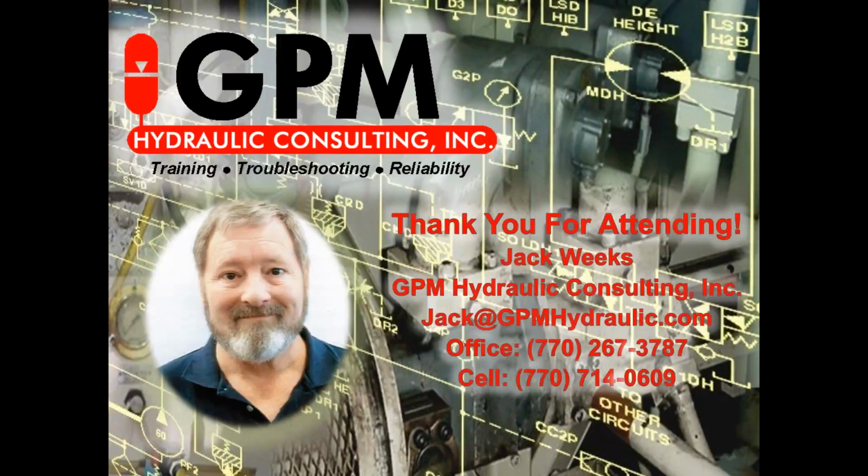If the pump is badly worn, then it's not strong enough to cavitate. You know, most people think they hear a pump cavitate, oh, we've got to change that pump. A lot of times they change it and the cavitation goes away. Well, what happened was they fixed whatever was blocking the suction line by changing the pump. If a pump's strong enough to cavitate, it's probably strong enough to do its job. If you can correct the problem, it's reduced its lifespan to some degree, depending on how long it's been cavitating. But usually if it can cavitate, it can do its job.